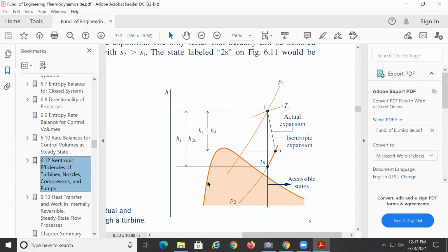So here, what happens when you go to a turbine? What is the function of the turbine? Generally, what was the model for the engine on an aircraft? You first have a compressor because you want to take the atmospheric pressure and compress it, so you increase the pressure. Then you burn the fuel, so you increase the internal energy, so you have pressure times whatever is the volume of the control volume plus internal energy. What is that equal to? The enthalpy, no? Okay. Now, what is the role of the turbine?